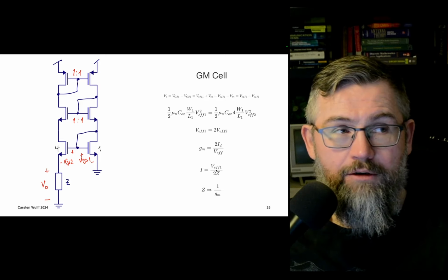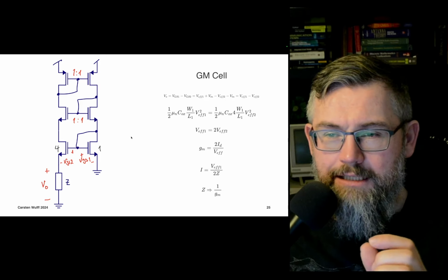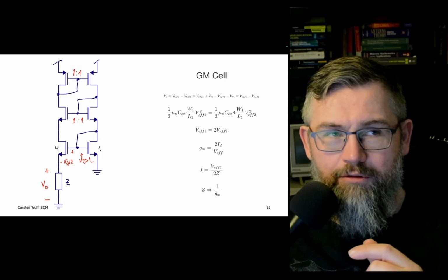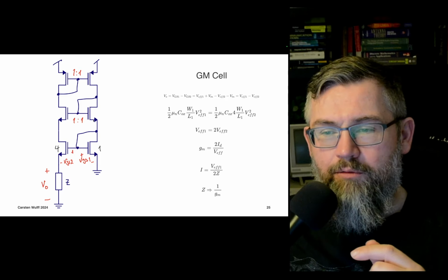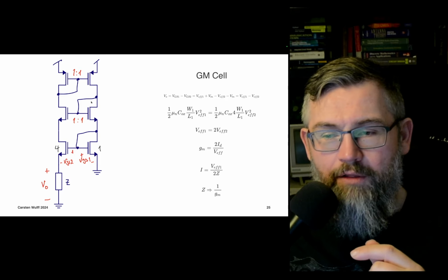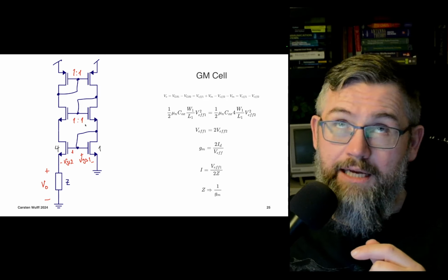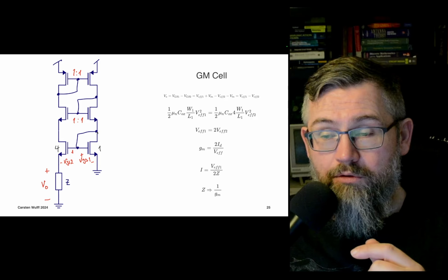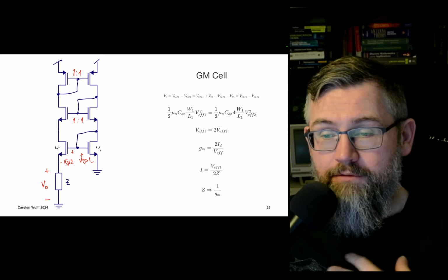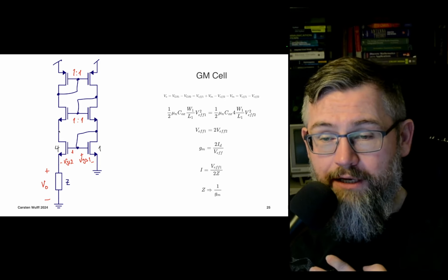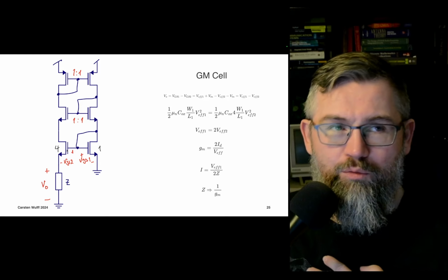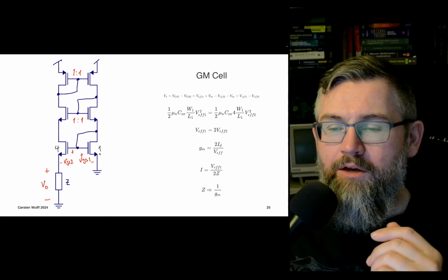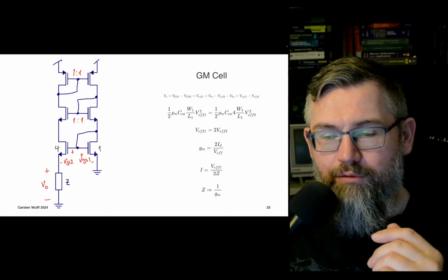There's a lot of equations, a lot of drawings. Okay, let's start first with a circuit understanding. Here at the top we have a PMOS current mirror. At the bottom here we have an NMOS current mirror. That just acts as a cascode, or not as a cascode, but as a voltage copier. So it'll take the voltage at the drain node and gate node of device 1 here and copy that to device 4. Actually, the 1 and 4 is the size difference. And then we have the NMOS at the bottom, where we have a 1 to 4 size difference.